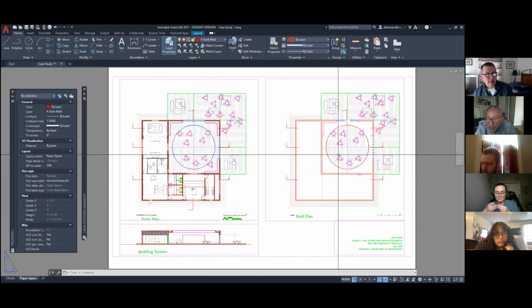I always put you're going to spend about 90% of your time in AutoCAD in model space doing your drafting. Paper space is just for really laying things out. It's for preparing this, particularly if you have multiple views like this sheet, preparing it to be printed out.